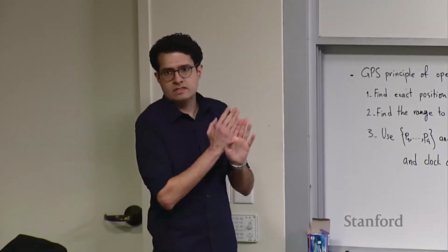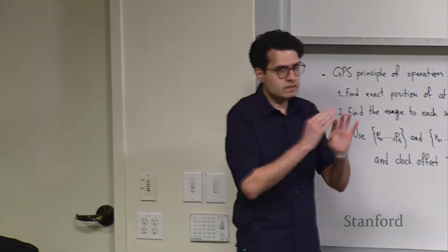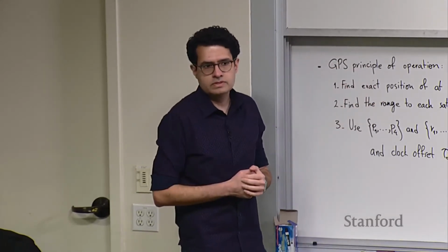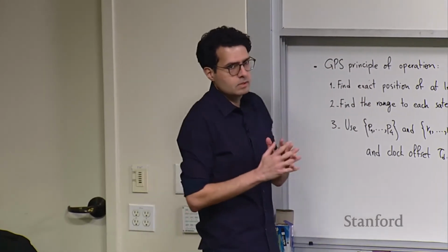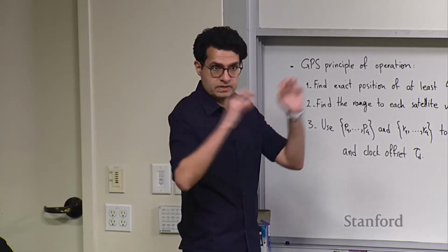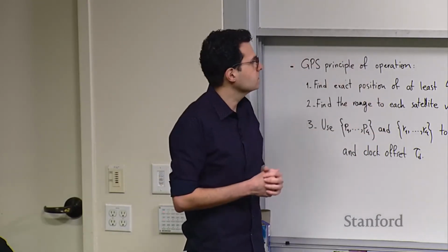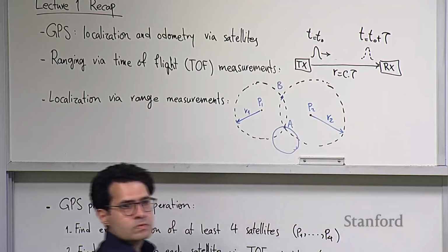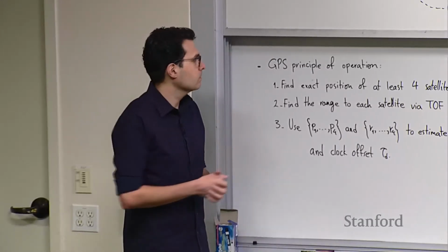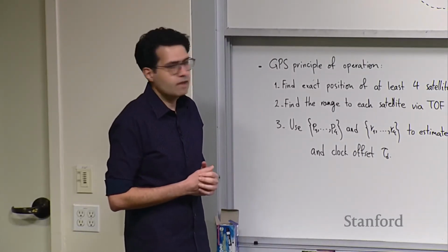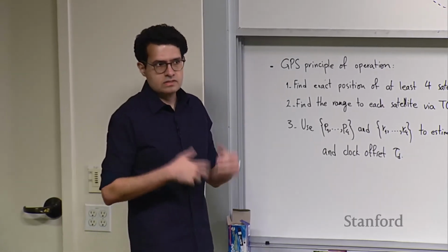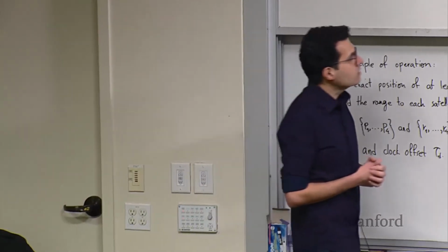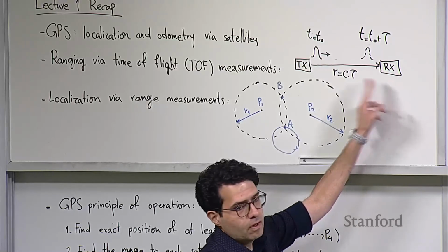In the real world, that's never the case. It is the case between the GPS satellites. So the GPS satellite systems, these 30-something satellites that are orbiting the Earth, have very fancy, super well synchronized clocks between them. So that's kind of like your standard reference clock system of the GPS. But our receivers, our phones, our laptops, our car GPS systems, or whatever receivers we have, do not have perfect clocks. These are cheap electronic clocks based on oscillators and things like that. So our clock is always going to be offset from the GPS reference clock.